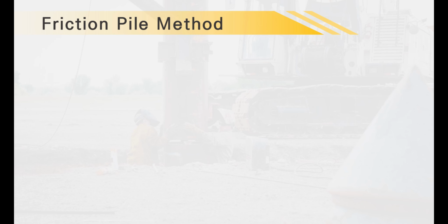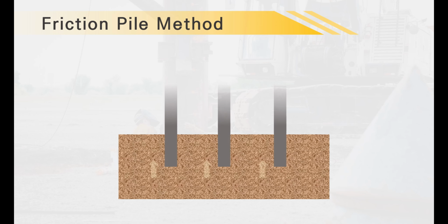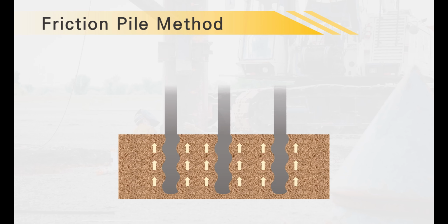Among the methods, friction pile foundation was chosen. Friction pile foundation uses the frictional resistance force between the pile surface and the adjacent soil to transfer the superstructure load. Depending on the subsoil condition, resistance force due to friction can develop into the full length of the pile. Also, the friction pile tends to have a large surface area, which gives it enough resistance and relatively does not require a hard stratum.